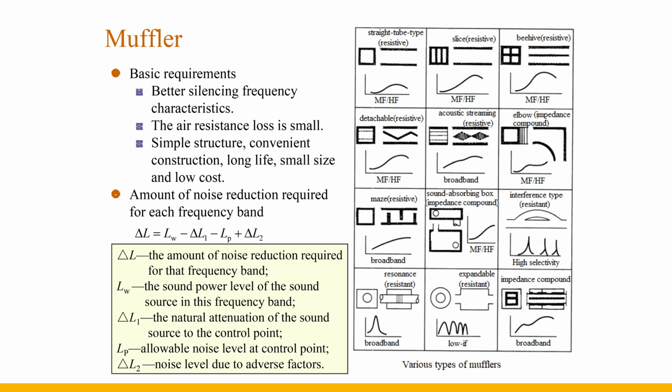It can be emphasized according to the actual situation. The design steps of the muffler are: the first, calculate the required muffling amount for each frequency band according to the frequency spectrum of the noise source and the noise control standard.